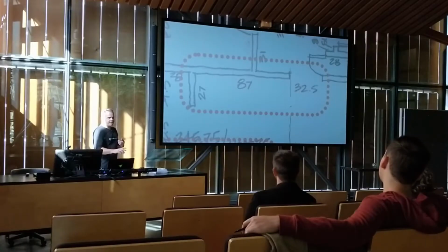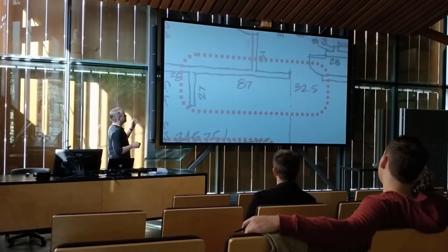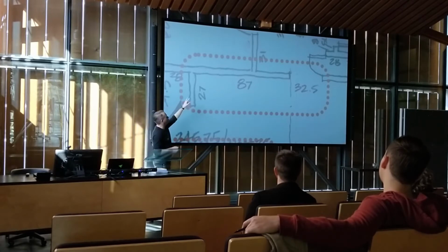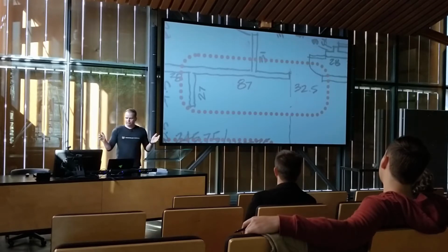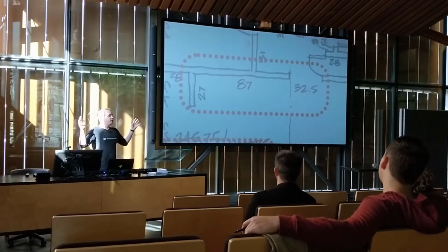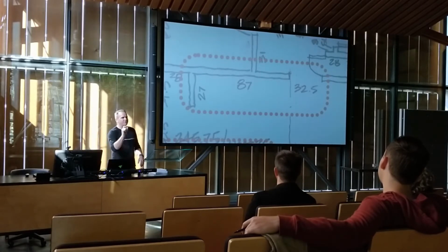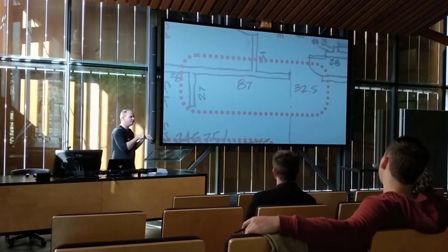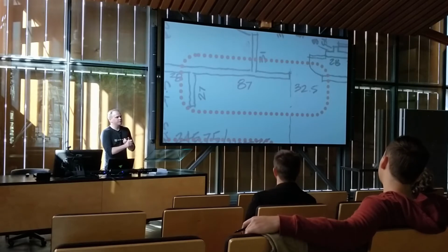So I'll do 27 from break to break. Here, this thing goes from wall to wall is 27, and from this wall to the door is 87. And then the opening there is 32.5. I say 32.5 because if I do 32 and then 1/2, it gets messy immediately. The other reason is that my default units in SketchUp are decimal inches, so I can just type 32.5, enter, and that's going to get me that dimension.